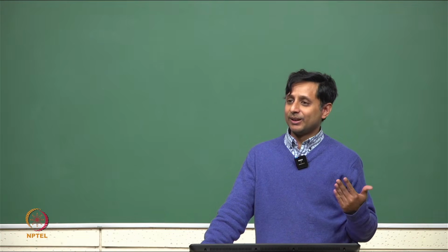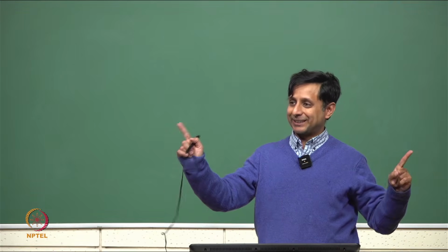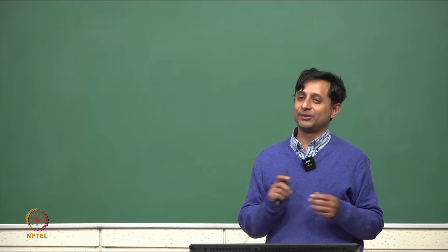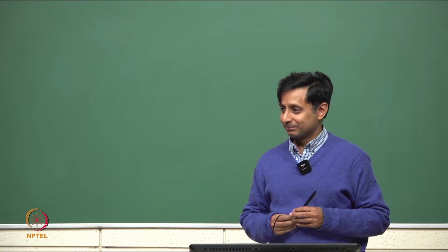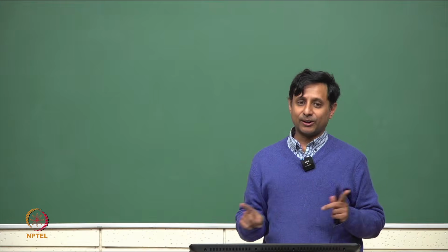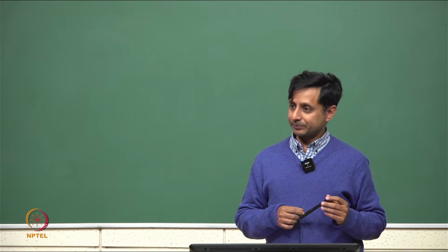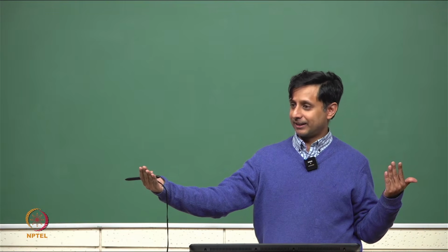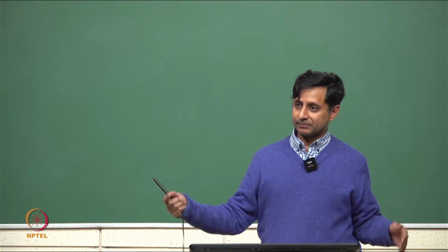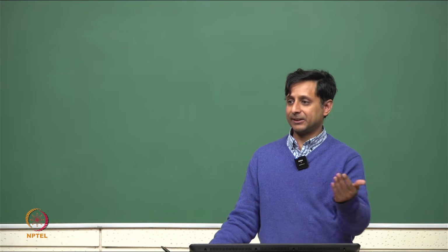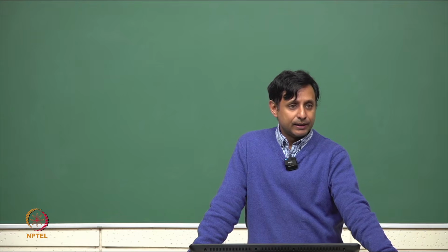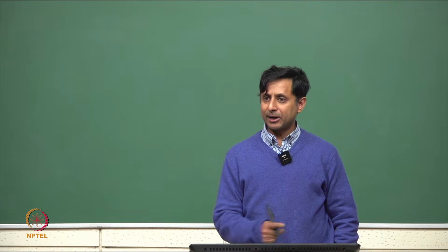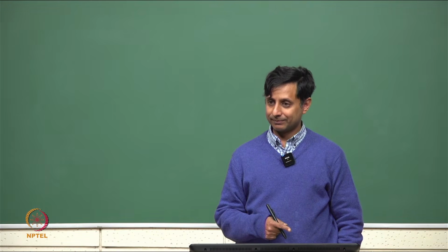All the dot products are going to be equal to 0, and whenever you are applying Tellegen's theorem, what you really have to do is the mixed dot product. The self dot product equal to 0 is not going to get you very far. The mixed dot product is always going to be helpful. Voltages of one experiment dot product with currents of the second experiment, and voltages of the second with currents of the first. Fine. This is how you apply Tellegen's theorem. The second part of the proof is just the same.